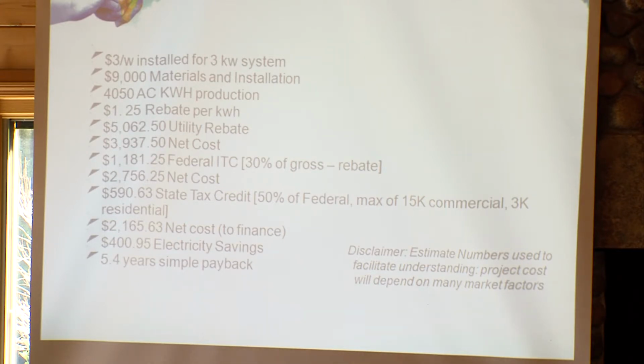So it'll all just depend on how far away you are from where the equipment can be delivered, lot of things there dictate, but I can tell you that for roof-mounted systems in Iowa, the cost is coming down. It has come down even in the last year, and this $3 per watt installed is really not that far off. And it can vary from $3.28 to $3.50. If you're doing a large installation, it could be even $2.82 per watt installed. So again, it's just going to vary.